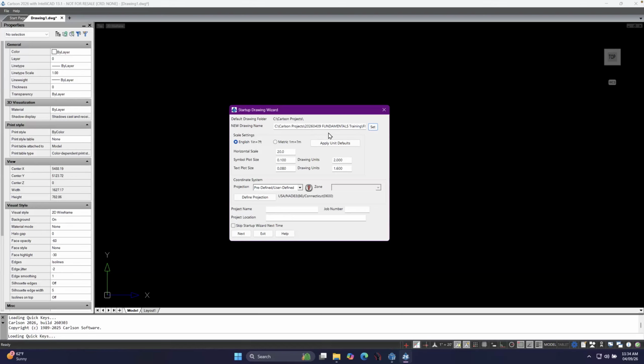So that example one is an existing drawing that you don't want to open. You could, it wouldn't hurt, but all right, so we've got a new drawing name. We've named it. In which case you can see it's all sitting here in my folder, and I called it first example DWG. So once you have that name, hit the next button at the bottom.